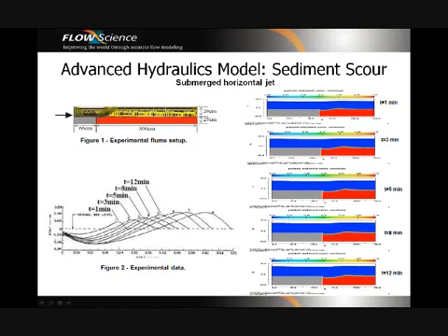Figure 2 shows the time evolution of the packed bed profile based on experiment. The column of plots at the right shows the predicted profiles from Flow3D simulation. The domain has been truncated in these plots so that only the edges of the apron and the first section of the bed are visible. The shape and the height of the predicted bed profiles compare well to the experimentally observed sand bed.